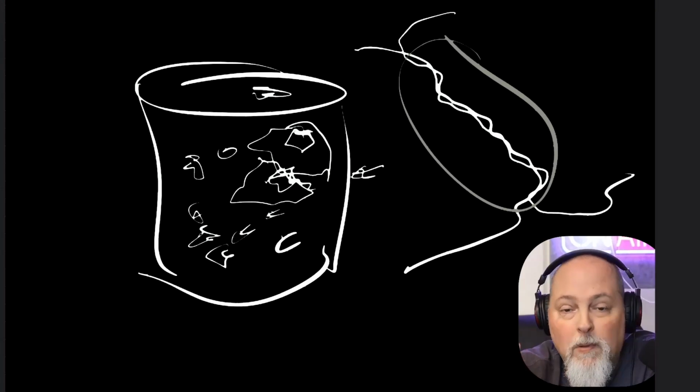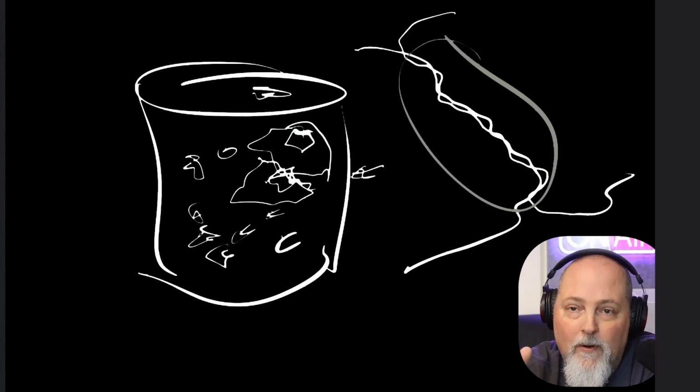Basically it acts like a roadblock that makes slip harder. And slip is where, if you listen to the podcast episode, you should have a really good idea of ductility and slip and all those terms. But grain boundaries can also become weak or chemically active regions where corrosion or creep damage may get in more easily. And the grain size matters.